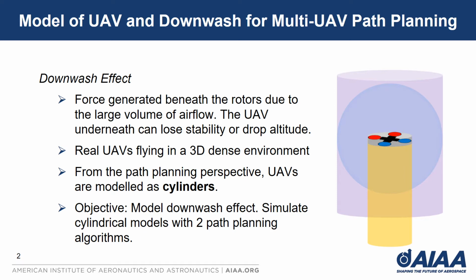So downwash is the force generated underneath the rotors due to the large volume of airflow, and the UAV underneath can lose stability or drop altitude. It is an issue for real UAVs flying in a 3D dense environment because it can easily cause collisions. To prevent collisions, it is important to find out how significant the downwash effect can be.